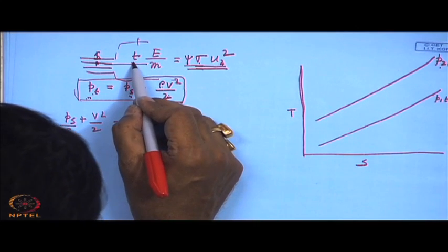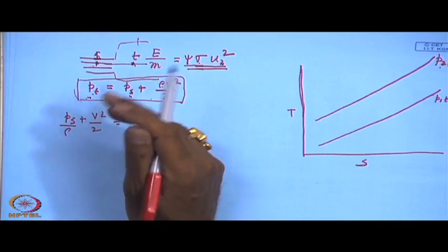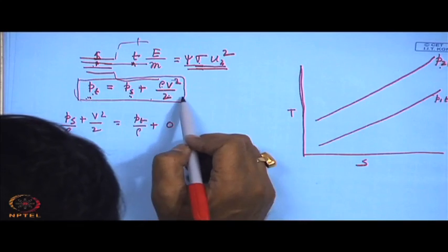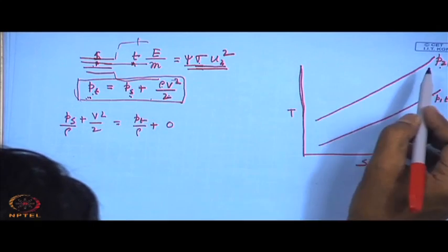That means the total pressure is obtained by writing the Bernoulli's equation, which means that the fluid is decelerated isentropically. Isentropically means without any internal irreversibility, without any heat transfer, therefore external irreversibility is also not there, purely reversible way, and without any other energy added or taken out. So therefore this is the concept of the total pressure.